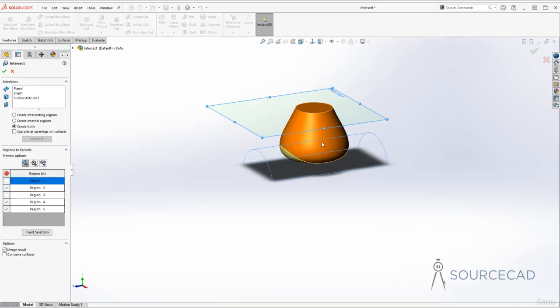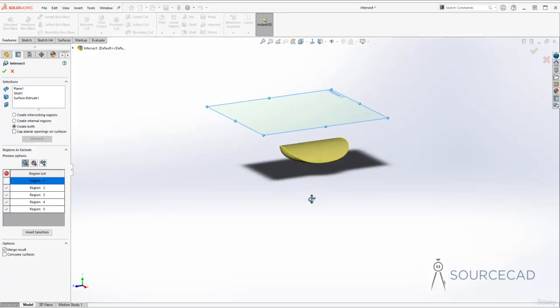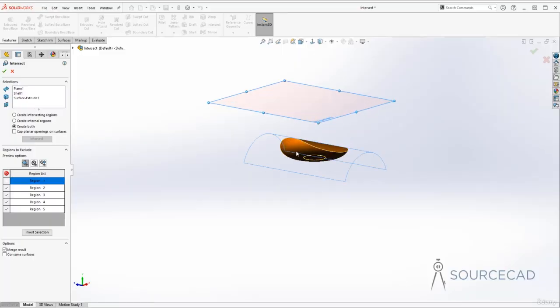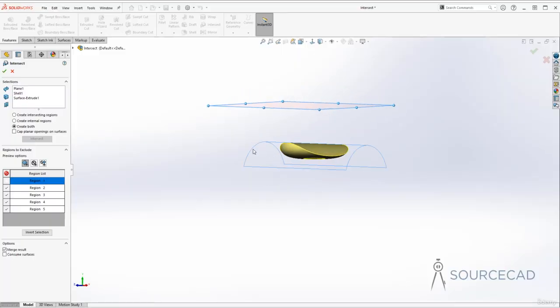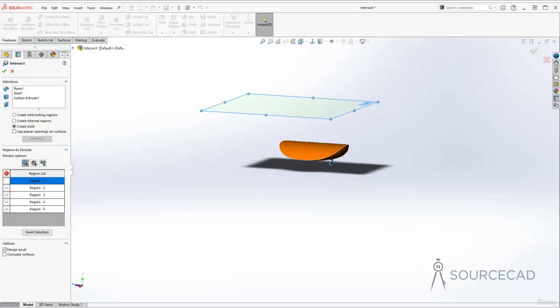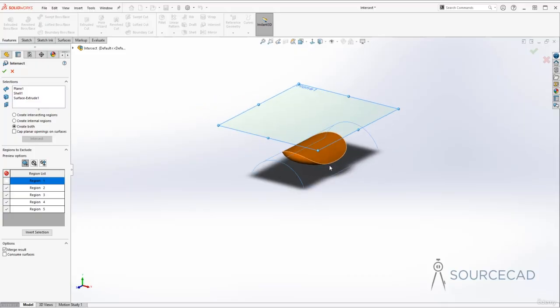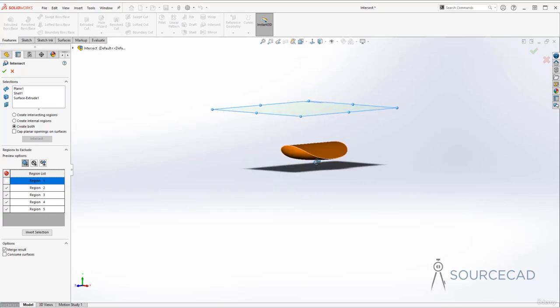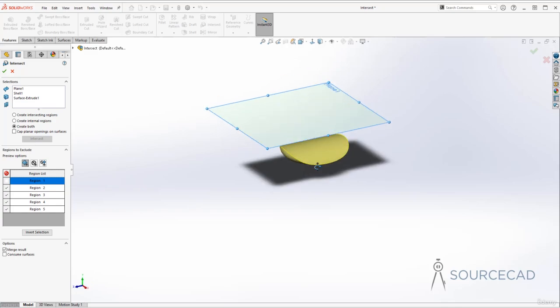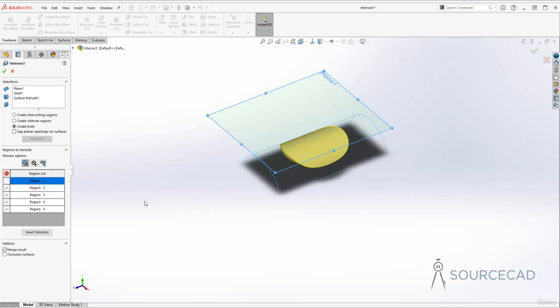It was initially hollow, but SolidWorks created solid inside this. So click, and there we are. And that's the final region, which is basically again a negative space, created inside this surface and the bottom part of that jar. So that's again a hollow shape, which we ended up with as a solid now. Alright, so that's how it creates all these features. Now I'm just going to uncheck all of these options here so that everything is back in the drawing.